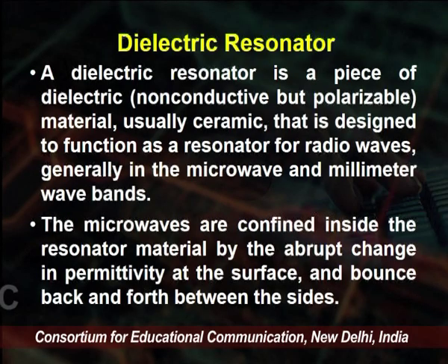So, the microwaves are confined inside the resonator material by the abrupt changes in the permittivity at the surfaces and bounce back and forth between the sides. At certain frequencies, the resonant frequencies, the microwaves form standing waves in the resonator, oscillating with large amplitudes.